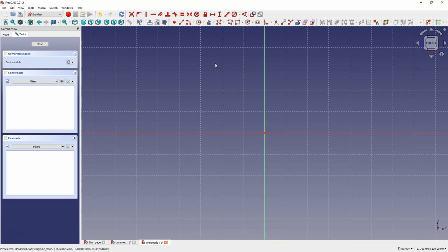We will create a shape consisting of several lines, and when it comes to drawing lines in FreeCAD, we have the line command. And this command works in such a way that we draw individual lines. Now, if I want to create another line linked to this line, I click here to link the start of the new line to this point and define the second point. In this way, I can create subsequent segments of the sketch. Here I remind you that I have automatic constraints enabled, which allows me to link the next line to the end of the previous line.